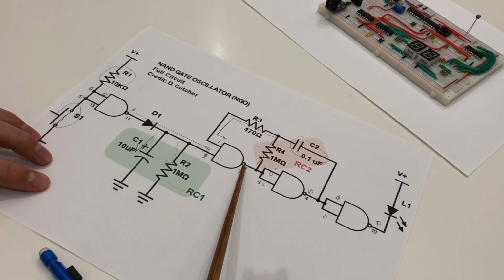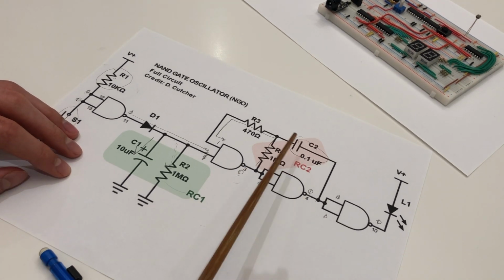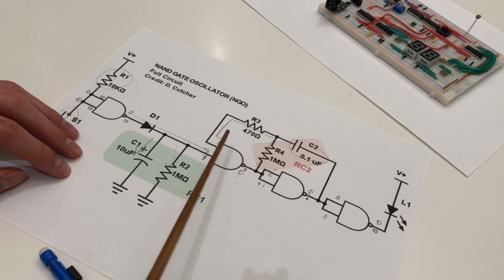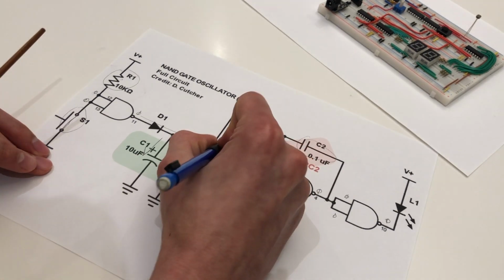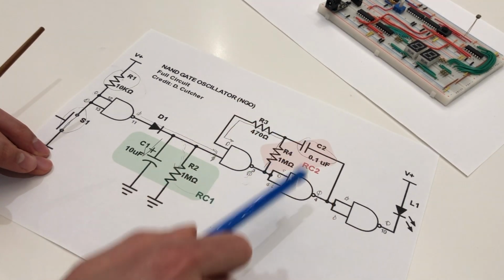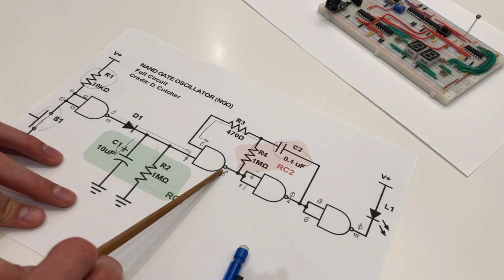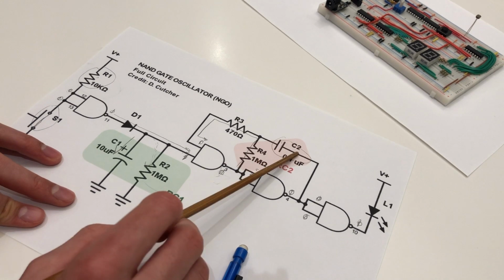After pin 3 is low, C2 discharges through R4. Once the capacitor's charge falls below half of the supply voltage, pin 2 of the NAND IC reads the signal as low. This means that the output of pin 3 is now high, so the LED turns off. When pin 3 of the NAND IC turns high, C2 begins to charge again.